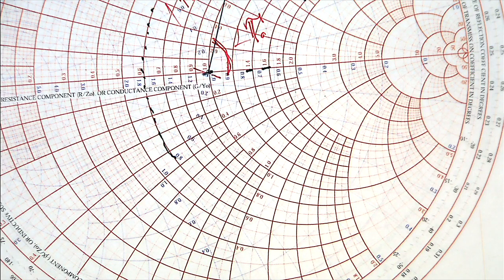Again, if I select the length of the transmission line as this number, then this transmission line acts as an inductor. For example, if we have a 2 picofarad capacitor and I want to make a transmission line that acts as a 2 picofarad capacitor, with the intrinsic impedance of 50 ohm at 3 gigahertz with the phase velocity of 0.77 of C, then the length of the transmission line that I should pick is this value. Or for an inductor of 5.3 nanohenry, the length should be this value.